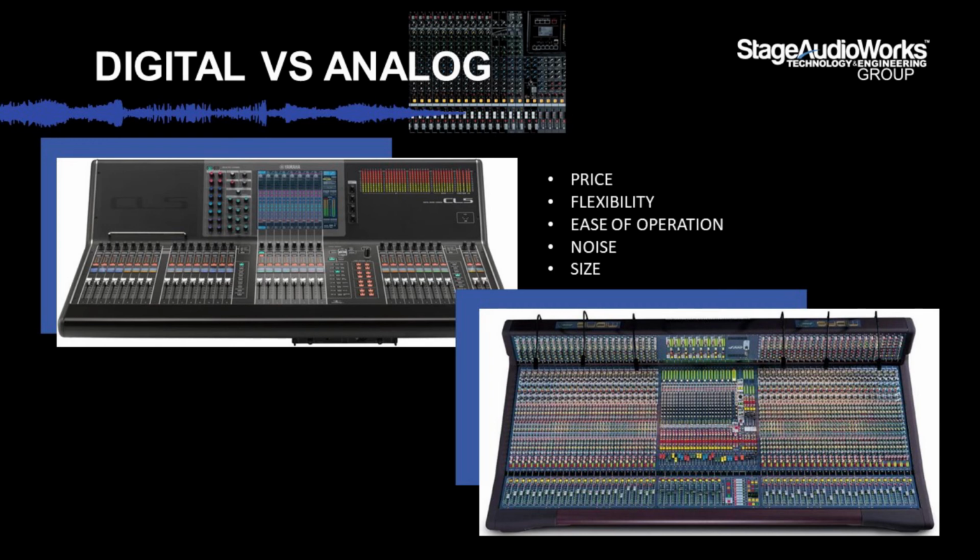Flexibility. Digital consoles are far more flexible than their analog counterparts. So you're able to save entire shows, each with their own channel settings and parameters, and recall them instantly. You can program ahead of time and recall your show off of a memory stick. You can store presets for effects, EQs, compression, and load them onto specific channels. In analog, you obviously have to do all of this manually, and you have to edit each parameter manually for each show or application. So you'll often see guys running analog. You'll look at their outboard gear rack, and they've got printed little diagrams showing where each parameter pot should be sitting in case something gets changed or bumped.